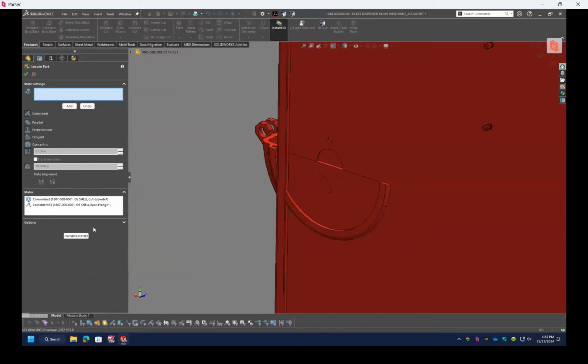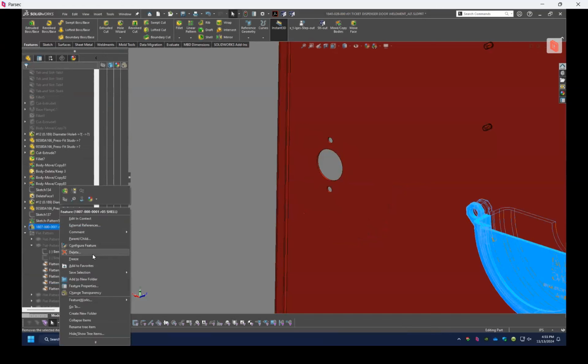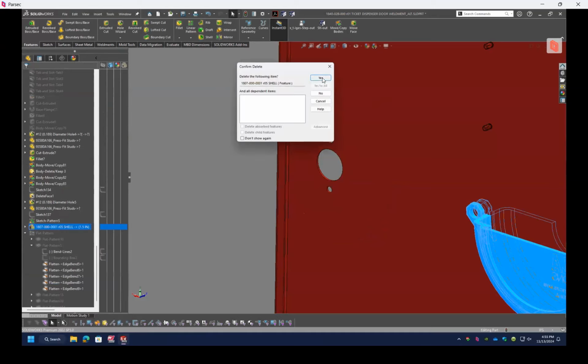You do only have the simple mates. So this is really for simply putting solids together. You're not going to do a slot mate or a mechanical mate, a more complicated scenario, but you can position it where you need to. You also have the benefit, in some ways over an assembly, that nothing is floating. Once I accept that's where I want the part, it stays there. There is no moving it accidentally. Sometimes in an assembly, you didn't have it fully defined with mates, and it gets moved off the page and you didn't realize. That doesn't happen here, which is kind of cool.